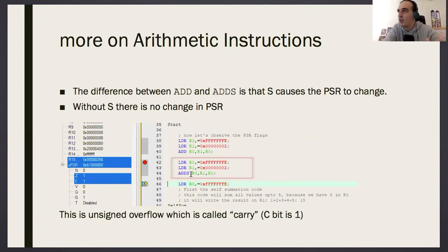This will be a way of handling this: just imagine you didn't understand something. Okay, how does it work? Does this operation change the flags, or what value will the flag have, or what register value will I get? Write the code, debug it, and check the registers and see for yourself. You have this capability. You can do this with a card, and actually without a card using the simulator. The usage of the simulator, the usage of the card, usage of Keil, how to debug, how to load a code in your card, everything will be demonstrated in the first week of the labs. But after the first week, you'll be expected to perform.